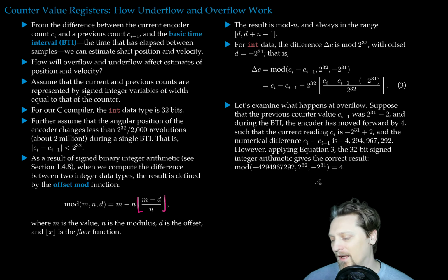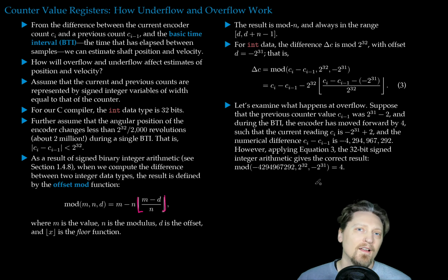Okay, so that is how to measure the angular position and velocity of a motor shaft using an encoder. Quadrature encoders in particular are what we've focused on. We've also seen single channel encoders and absolute encoders as well. We've seen how to implement the encoder count measurements programmatically in the MyRio. So, all right, we'll see you in the next section.